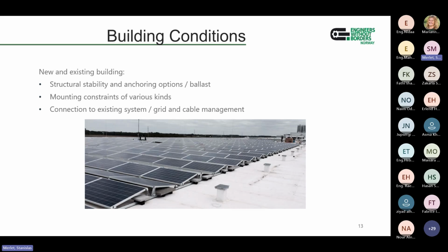One solution that we found, which is quite interesting, was that there was an old railway around, and we could actually take whatever we wanted from there. So we used old parts of the railway as ballast for the mounting system, in some kind of cages directly mounted on the structure. We put this old metal stuff in the cages, and that acted as ballast, and that proved to be quite efficient. That was built 10 years ago, and it hasn't moved, and it's a very cost efficient solution.